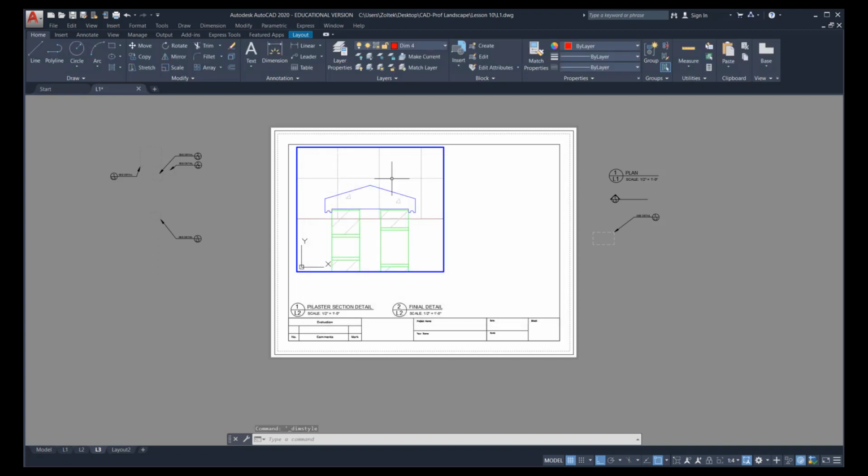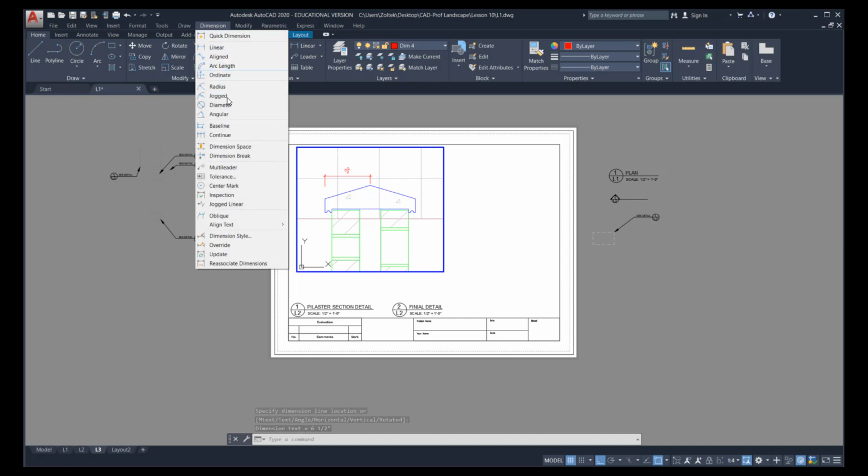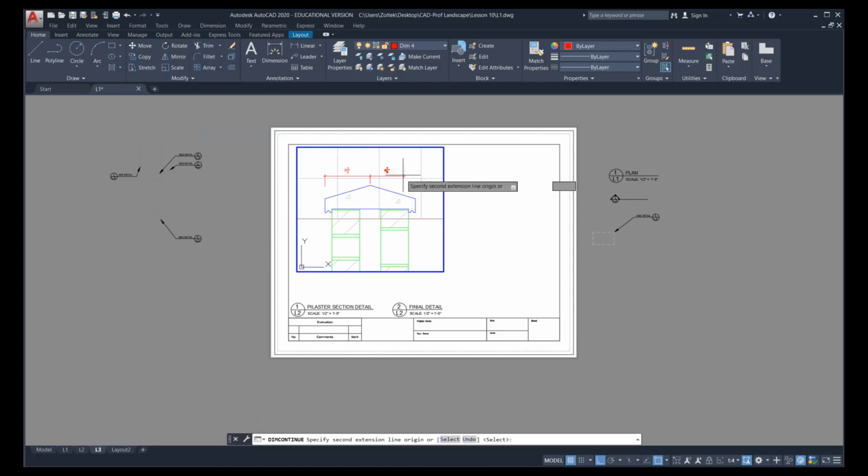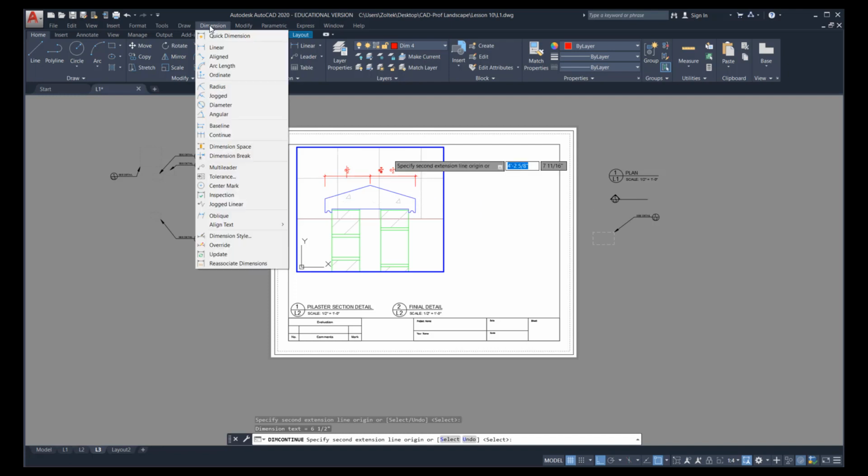And now right in this viewport I'm going to dimension it. I caution against it, but at this point you need to practice some of these new techniques. So I'm going to click on linear. There's my first point, my second point, and move that up. There's my 6.5 inch dimension. Select dimension, continue. Click the other side of the post. Great. Select dimension, base point.